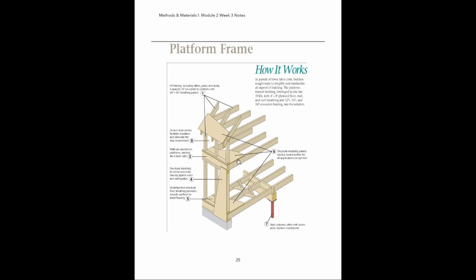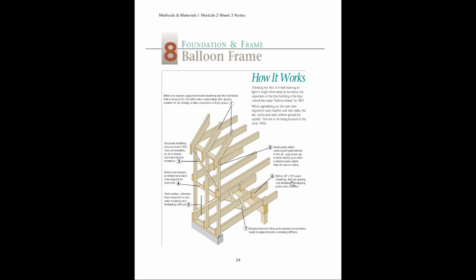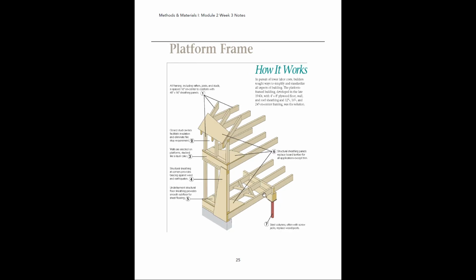And then here you can see, comparing this to the balloon frame, these joists that are coming through here, they don't overlap like they did here. They're actually butting up to one another. Well, they're butting up to this additional board that's running down between them. And then all that is sitting upon, again, these three large beams that are sistered together right here. And then those are sitting on top of steel columns that are running down to the basement floor.